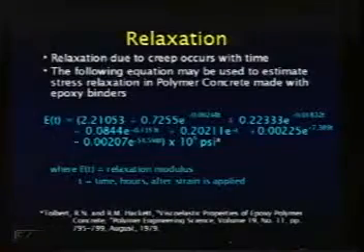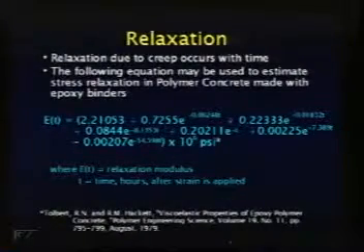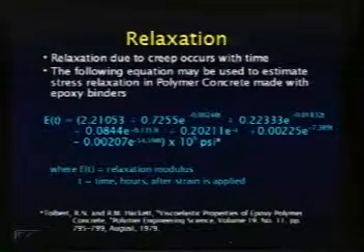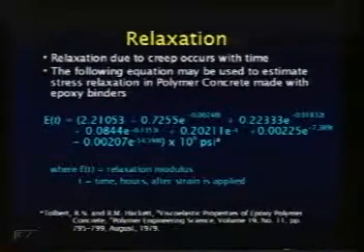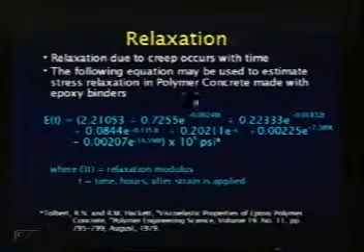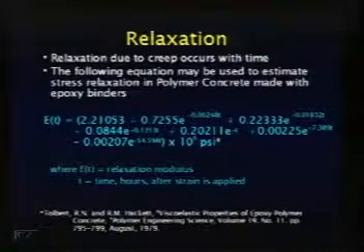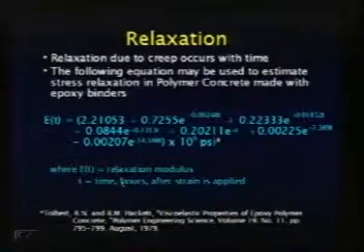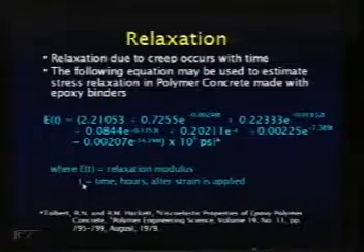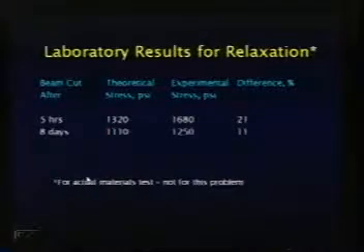One of the things that comes up sometimes is relaxation. We know that polymers relax due to creep. There's not a lot of good data out there for that, but we did find a reference in the literature. This is a fairly long, involved equation for the modulus of elasticity as a function of time. It gives you really the relaxation modulus for a time t in hours. Well, that doesn't do you a lot of good, but I'll show you in a minute how we can simplify that down.